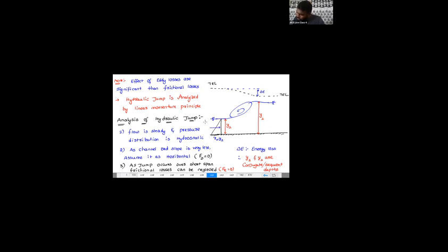And due to this hydrostatic force, we have FH1. Similarly, on the downstream side, the hydrostatic pressure on both sides of this element is gamma W into Y2. The force acting over here is FH2. I hope you remember I discussed these things in the case of uniform flow.